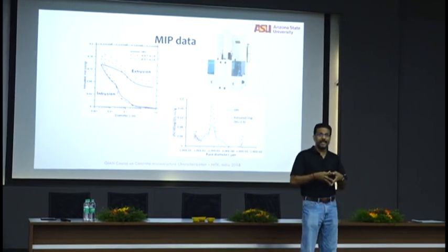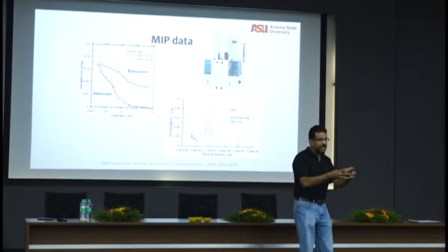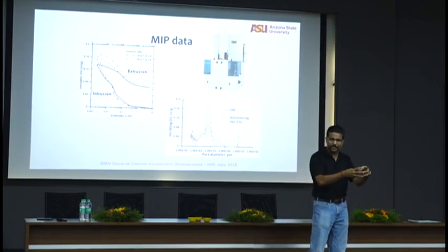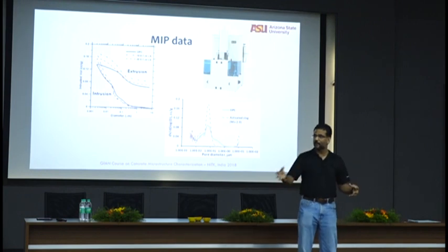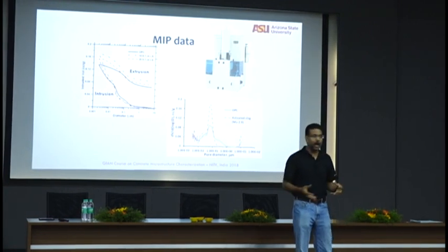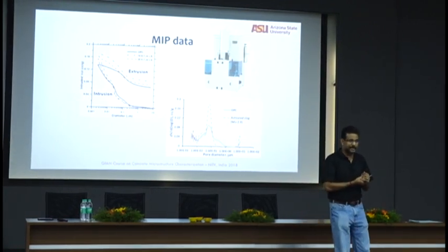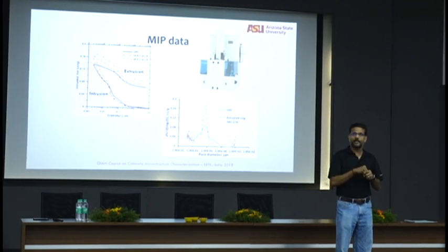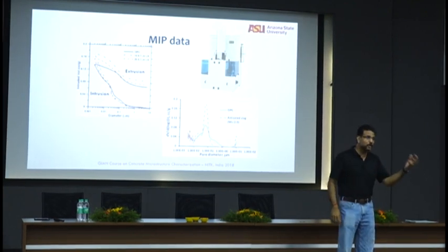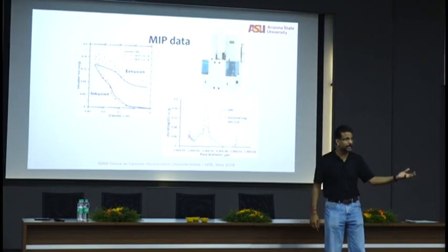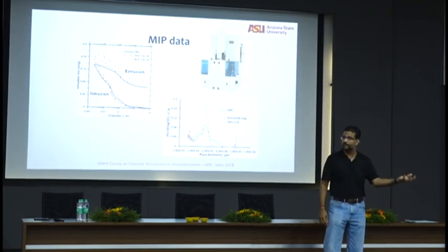But based on that, I know what I need as compositional starting points to make the 40 megapascal concrete. So I need the compositional correctness. If I want 40 megapascal concrete, can I start with just pure fly ash and mix it with water and get 40 MPa concrete? No, I know the composition of fly ash by itself is not good enough to give me a 40 megapascal concrete.